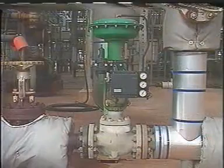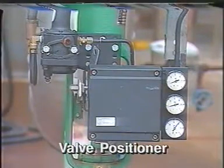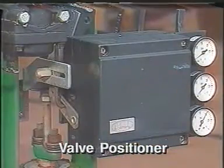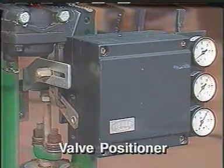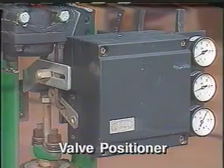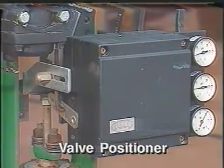Now, look at this valve. The black box with the 3 pressure gauges installed on the actuator yoke is called a valve positioner. Sometimes the maximum compressed air signal a controller produces isn't sufficient to move a valve stem or to move it fast enough. In these situations, a positioner helps the actuator move the valve stem.